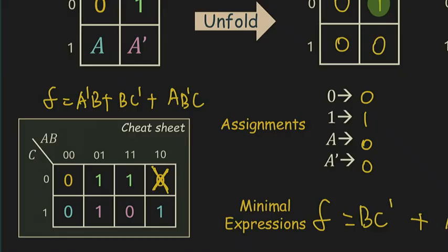So you can treat the x as a 0, put down 0 in the folded K-map, which gives you a valid but non-minimal expression. What about you treat it as a 1? You could, right? And 0, 1 will be folded into the A variable. And again, you get a valid expression by treating x as a 1, but you may not get the minimal expression. It really depends on what I need for that x in the final function. And in the workbook, you're going to explore a solution to this problem. Really, with some more careful design, you could design an algorithm that guarantees minimality in the presence of more complicated folding conditions.